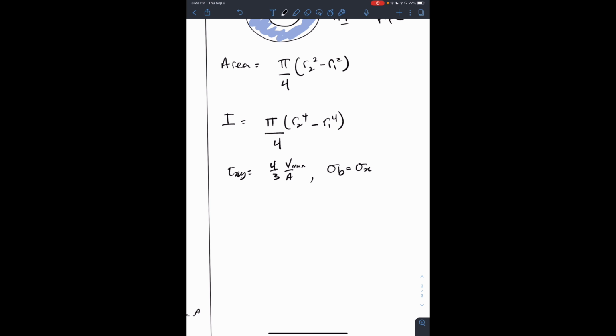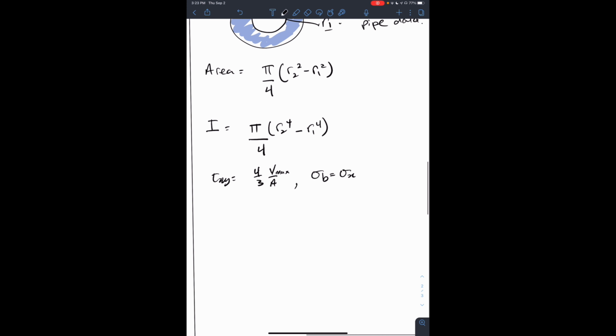So in order to stretch and compress, you need to apply a stress in that direction. So our bending stress is really sigma x, and we said that's our M max y on I, where y was our D on 2, and we have I from over here.